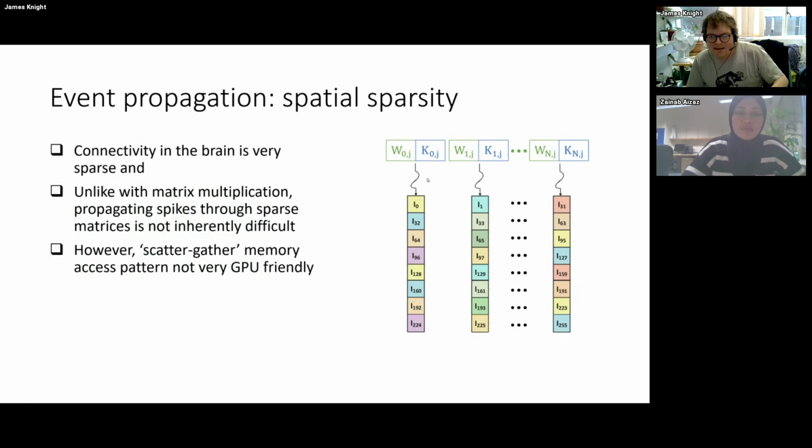And this index is basically pointing to a position in this lane local memory. So the weights are then sorted so that all the weights which connect to a target neuron with the same value modulo 32 go in the same lane. So basically, this first lane will be processing connections going to neuron 0, neuron 32, neuron 64, the next one to neuron 1, neuron 33, etc.